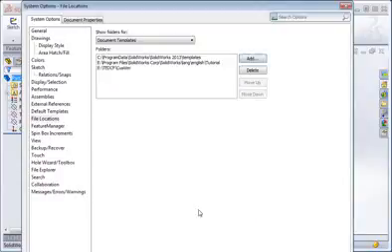Click OK to create the search path. Now when SolidWorks looks for document templates, it will look in the Custom folder in the TEDCF folder. Notice that you can move the search path up or down in the list. The order of this list sets the priority of the search path. You'll see how this works in just a minute. For now, I want you to look at the path at the top of the list. This is the search path that has the highest priority, so remember this path because you'll see it in just a minute. Click OK,